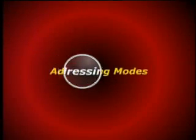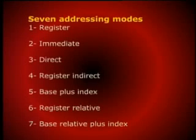Now we look at what the different addressing modes available with Intel are, and the general format of the instruction set. This slide shows the 7 addressing modes supported by the Intel processor. The first mode is register direct. The second one, a base with 8-bit displacement or a base with 32-bit displacement. The third mode is the indexed addressing mode.